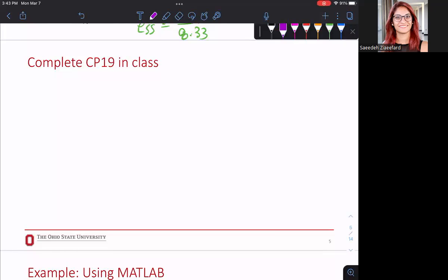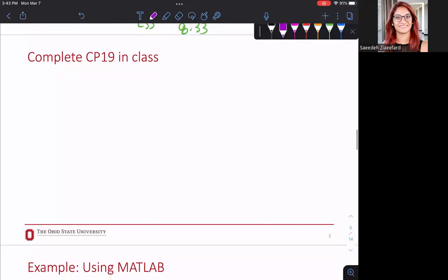Assume you have a step input. You always start from assuming you have a step input because you want to see the response of the system. You always check the step input. Then assume ramp input. Then check your system and see which one makes sense. That's all. All of the problems from here, the design.